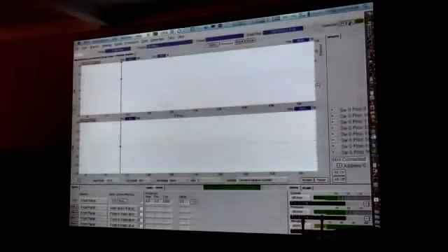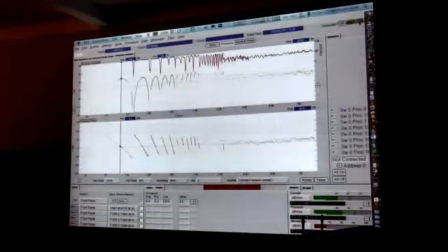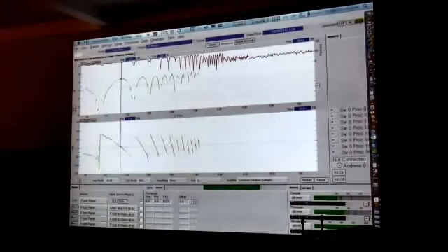Because if I play pink noise, this is a comb filter. Okay? In phase means no time difference, so no comb filter. You can have summation at 100 Hz with 10 milliseconds, but you will have cancellations at other frequencies. That is not in phase.